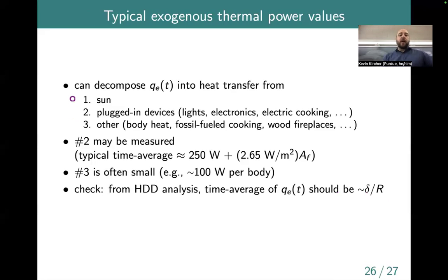Okay, so that leaves number 1. In our class on solar energy, we will talk about precise methods to calculate how much heat is gained from sunlight. It has to do with not only the area of the windows, but what direction they are facing. The amount of sunlight we're getting in from these windows is not very much, but those are getting direct sunlight, so they're getting more heat through them. It also has to do with what's called the solar heat gain coefficient of the window. Some windows are treated to reflect a lot of sunlight, in particular the infrared and thermal portions of solar radiation, some are not, and so on. There can also be shading devices and things like that. So it gets fairly complicated to do these more precise calculations.